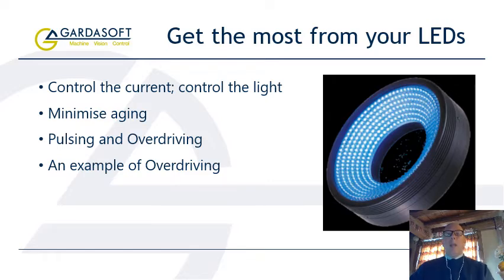In addition, LEDs heat up during use, and this changes both their forward voltage and their efficiency, so that brightness will vary over time. LEDs are remarkably reliable devices, but their light output will deteriorate over time as a consequence of repeated heating and cooling cycles. Typically, an LED would be replaced when its output falls to below 70% of its initial rating.